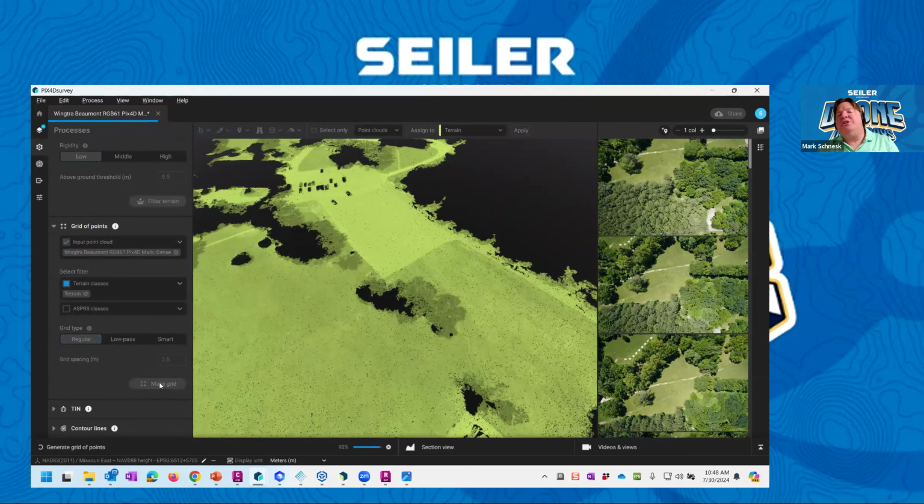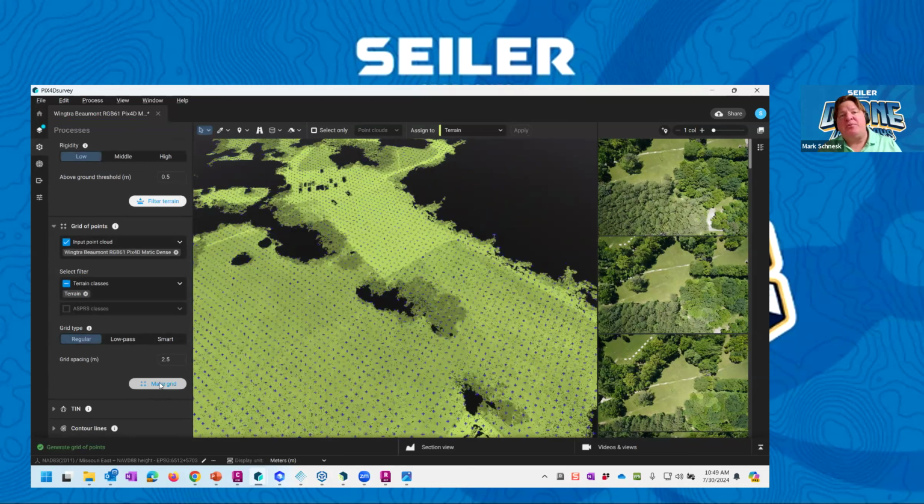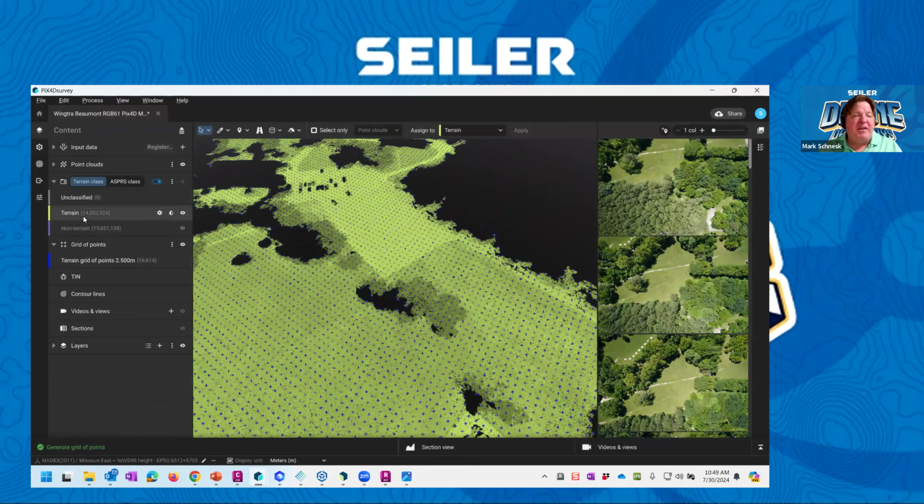The worst thing you can do is take this last file, drop it directly into Autodesk Recap, bring that to Civil 3D, or take that directly into MicroStation and try to create a surface out of 100% of the, I don't know, what do we got here? 100% of the 14 million points that I see. It's going to crash the system. There's going to be issues with the surface, and your computer's going to struggle and possibly crash every 5 minutes or so.